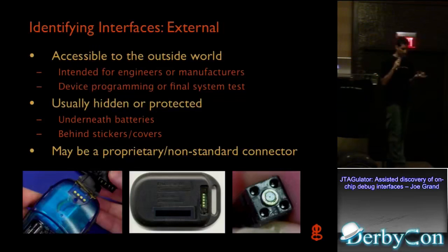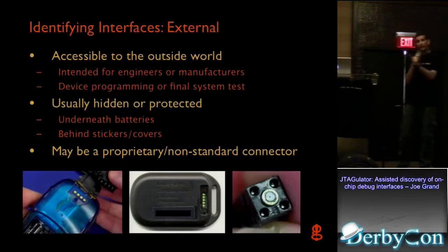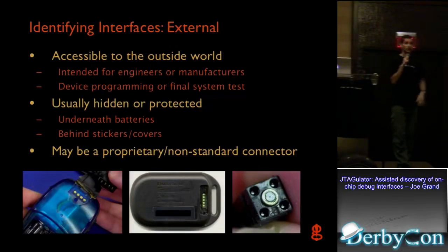Because usually the way the manufacturing process works is someone's making a product, you assemble the product, maybe do your testing, and then program it as the final thing. If the firmware changes, you don't want to have your part already programmed and have no capability to program it before it goes out the door. So that's a possibility. You pop the cap off and now you potentially have access to reprogram the device without having to open it at all. So that's external interfaces. Those are usually pretty easy to find, and when you do, the fact that they're brought out to the outside world tells you that it's probably something you should be looking at. But you still might not know the pinout, right? So that's the challenge.